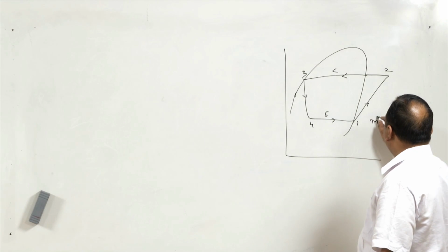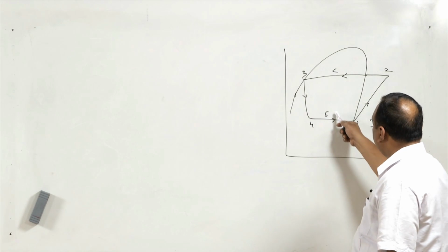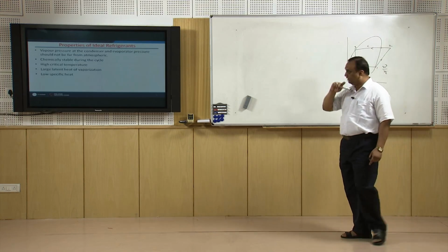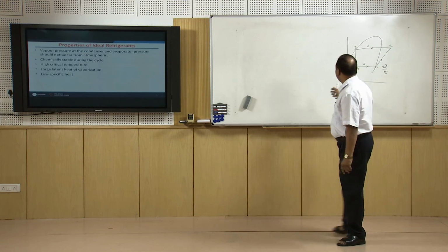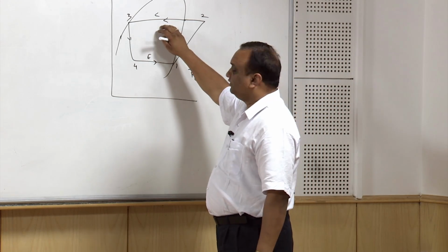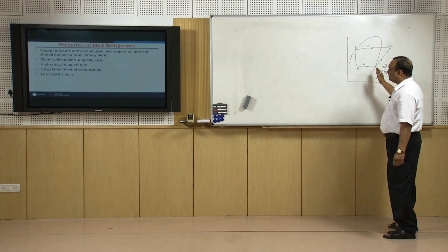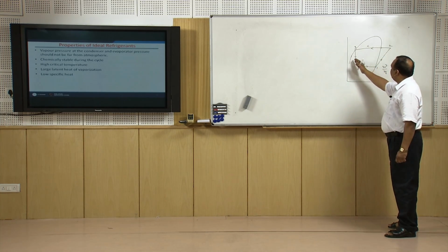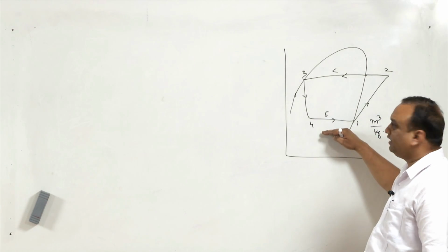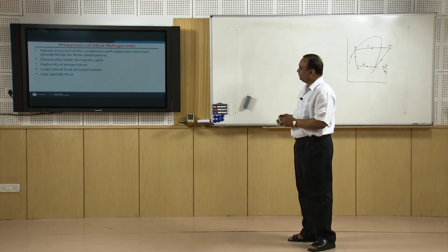Specific volume is meter cube per kg. So if 1 kg of refrigerant is in circulation, if evaporator pressure is low, then volume will increase and compressor will have to handle high volume of the gases, or the size of the compressor will be larger. So either way, pressure should not be very high in the condenser and should not be very low in evaporator. The ideal case is the pressure in the entire system is slightly above the atmosphere. So pressure in the evaporator is slightly above the atmosphere and pressure in the condenser is not very high. That is the very comfortable situation.